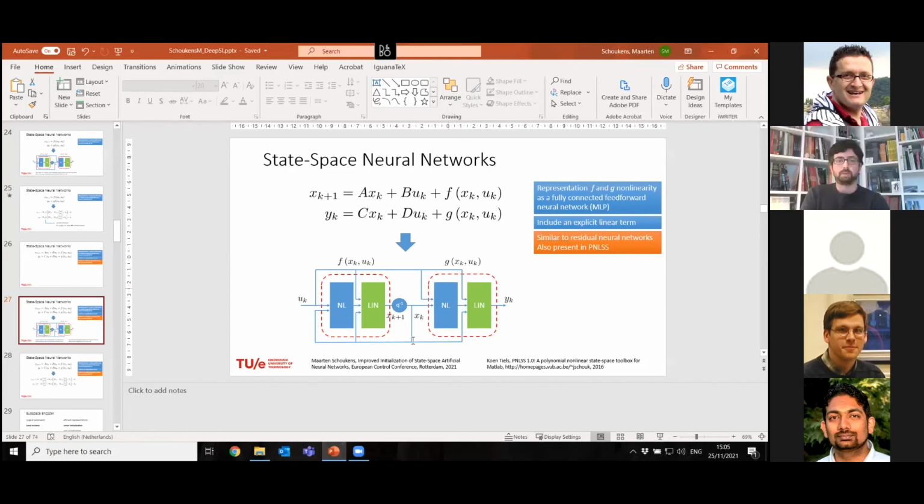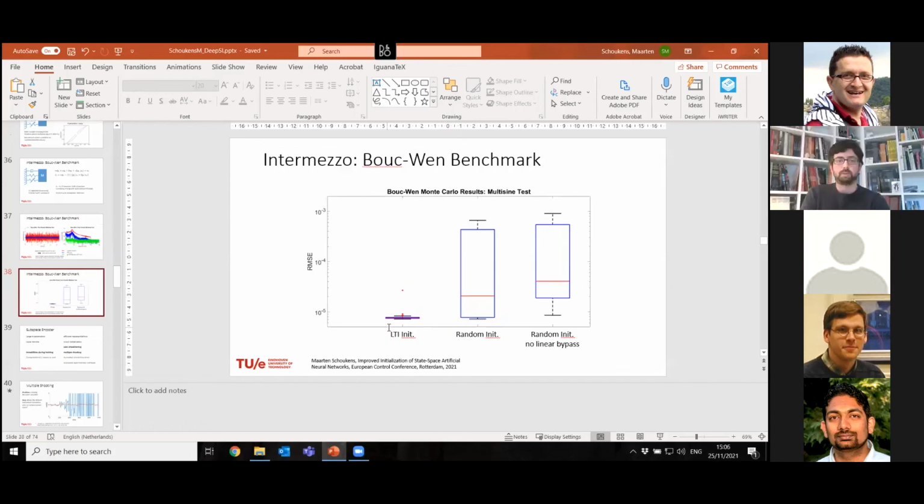Yeah, and I guess the test bench also has quite a strong linear structure in the hysteresis that you showed. It might even be good if you just extend the process such that you have an A matrix, but also a part which is, for example, a polynomial approach, like a cubic approximation. Then you would expect that the rest of the nonlinear function should be quite null.